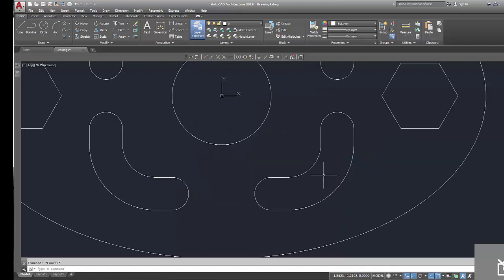And then we attacked the slot by drawing the center line of that slot, doing some offsetting, drawing the little circles at each end of the slot. And then we went in and trimmed up some of those lines and cleaned some things up by trimming and erasing. We mirrored that one over to the left and then both the slots up to the top.